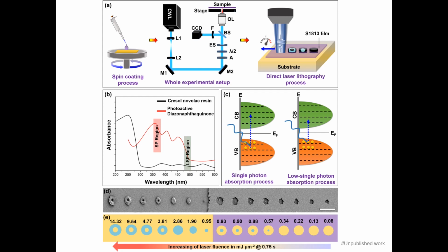So let me explain what is going on in this structure. Actually, this is a positive photoresist. Positive photoresist means once you expose and then develop, the exposed part dissolves, and you get the pattern. Here the photoresist acts as a positive, but at the center beam of the laser, it creates a chemical transformation of the positive photoresist into a negative photoresist, and it grows bigger and bigger.